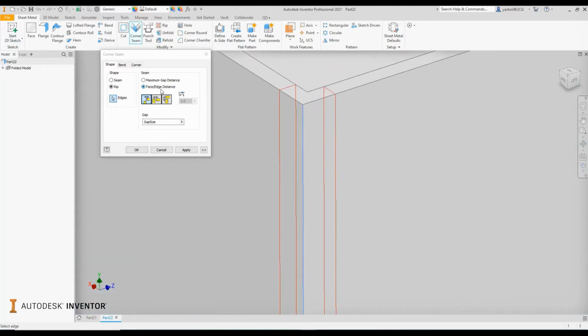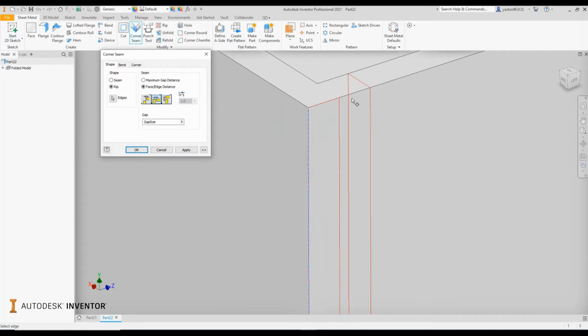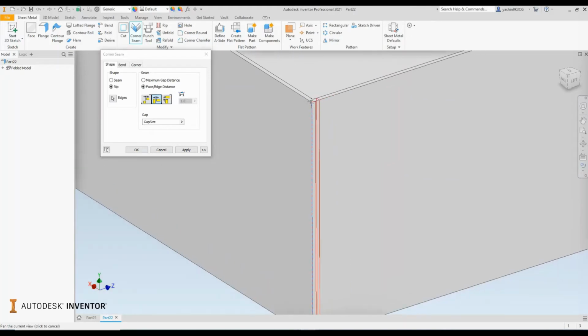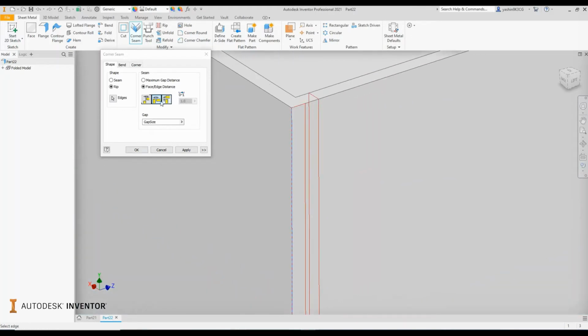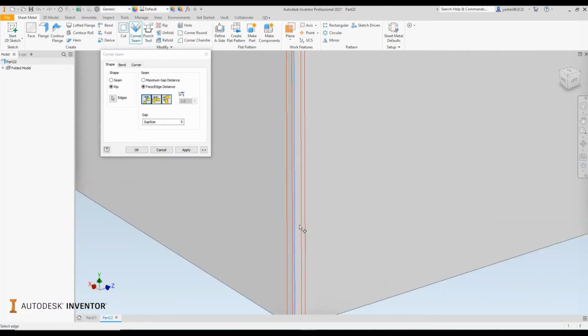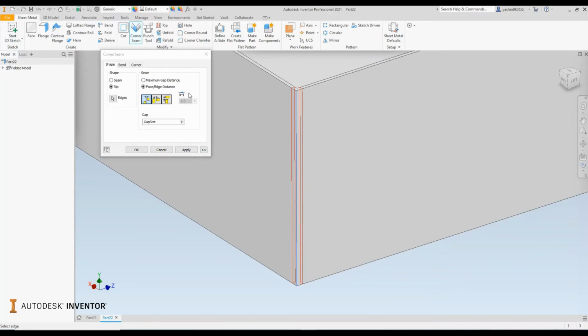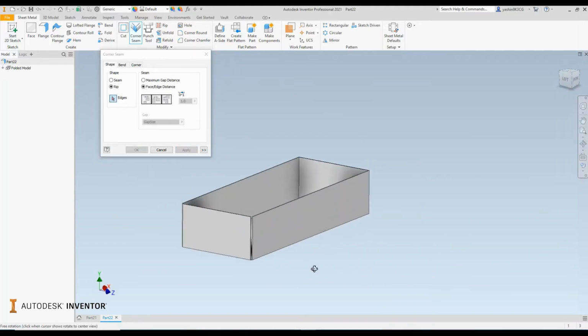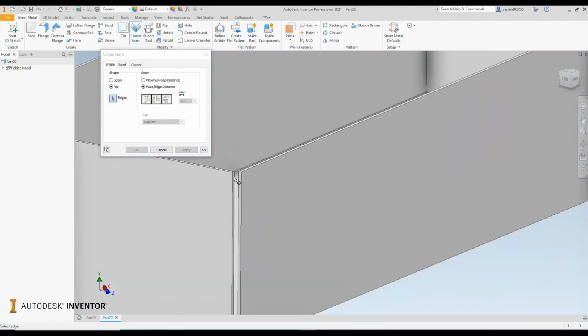There are a couple of toggles in your dialog box to define an overlap. Okay, so you'll see it's now extended and the gap is a little bit smaller, and the one side of material will be a little bit smaller. So you can use those options to define your gap distance on your edge. Once I've done that, I can simply select apply, and there we go. We have our two gaps that have been created.